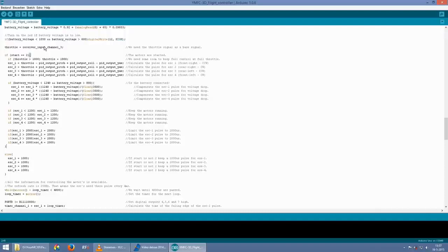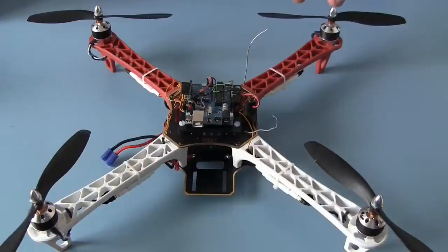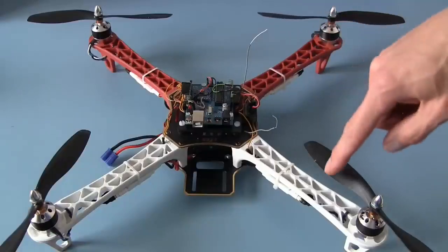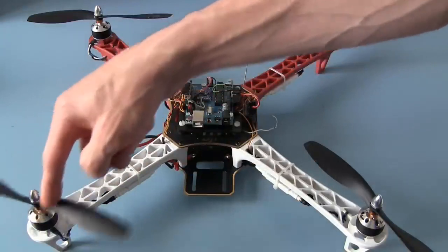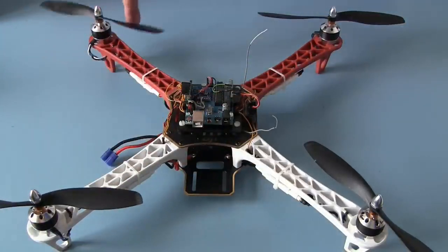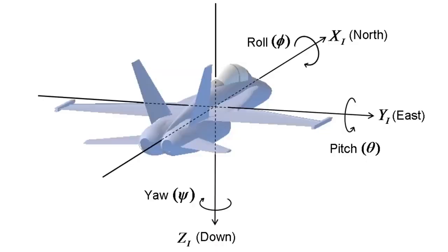Torque is used to yaw the multicopter. To do this, the RPM of the counterclockwise motors needs to be different from the clockwise motors. This is done by adding or subtracting the yaw PID controller output from the ESC pulses. Now motor 1 is rotating counterclockwise, motor 2 clockwise, motor 3 counterclockwise, and motor 4 clockwise. So when we want the multicopter to yaw right, the receiver input is a positive degrees per second value due to the standard of this picture.